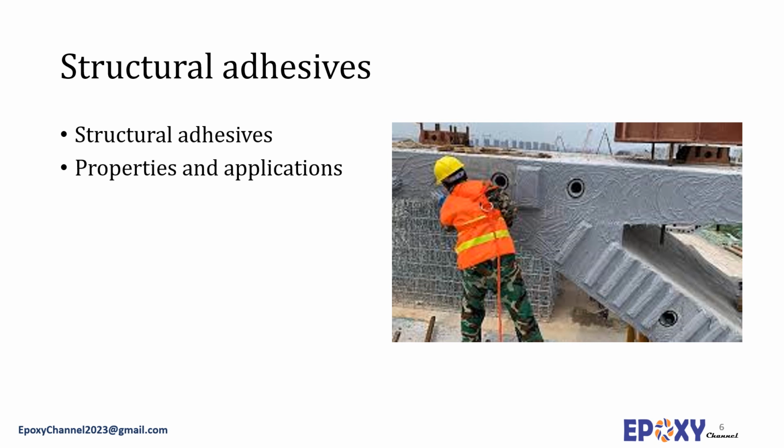Epoxy structural adhesives are also used in steel reinforced concretes, precast concrete objects, as well as anchoring steel bars in the concrete. Structural epoxy adhesives can be formulated to render various pot lives, making them suitable to be used in various conditions. Current commercially available epoxy structural adhesives are formulated as single component heat curing systems. However, multiple component adhesives that cure at either room or elevated temperatures are also available.